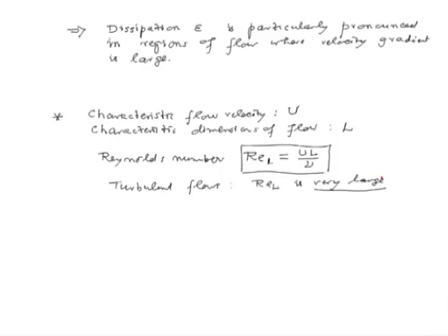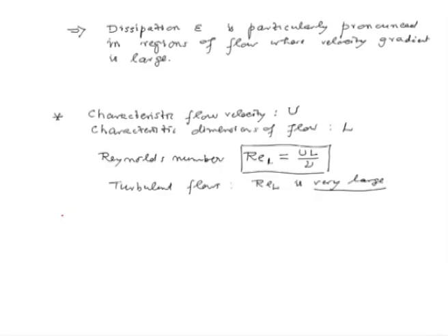In different situations we have got different limits on what we call the critical Reynolds number when transition from laminar to turbulence takes place. Okay. Now, these are a few defining things for us. We have got this Reynolds number and we have got our characteristic velocity and length scales, and then next we are going to talk about what we call eddies in our Richardson energy cascade.